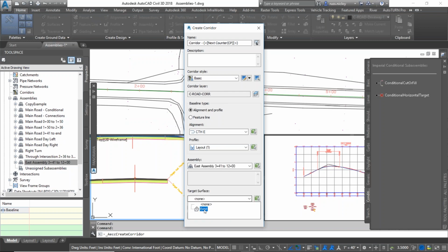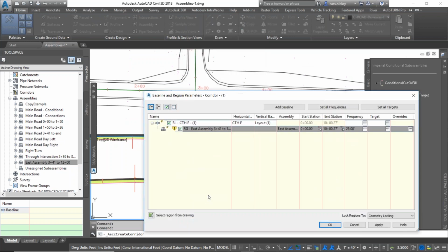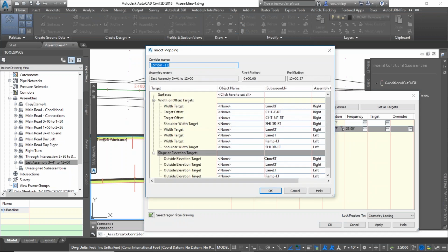Just assembly there, target surface. I'll say OK. And in the targets, I'll come in, and now it's much easier to figure out which one's which. The first one is the found one, and actually it got out of order because of that little switch that I did, but now I can tell that. I was in a real chance of saying, oh, the first one was not found, and assigning the wrong thing there. So naming there did get me out of a problem.